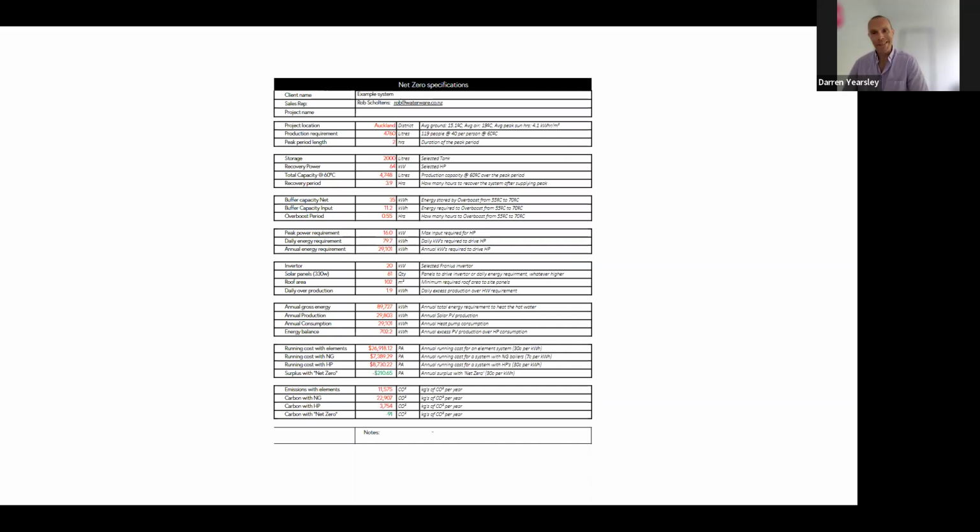When we do gas-based systems, because gas is very cheap in terms of cost per kilowatt, in terms of appliance cost, it makes sense to have a smaller amount of storage and a higher amount of recovery. So you can store a small amount of water and then you might recover it over half an hour or at maximum an hour, normally with a gas-based system.